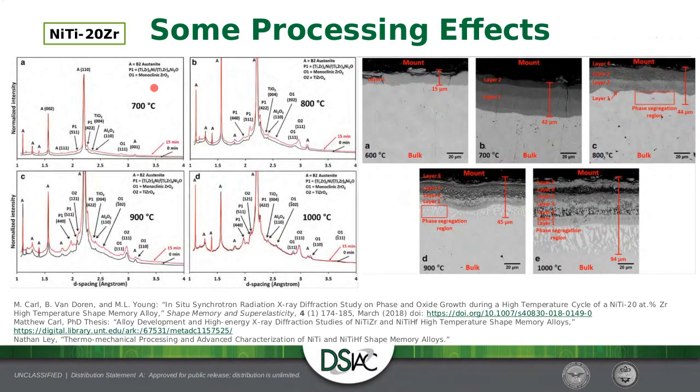I have also coupled that with SEM images, so you can see them over here. Mainly what we are trying to address is that you get cracking in these alloys when you try to roll them. What we found is if you go too low, you can have H-phase precipitates, and this will make it difficult to roll the material, or could lead to early cracking. So we need to go to hotter temperatures.